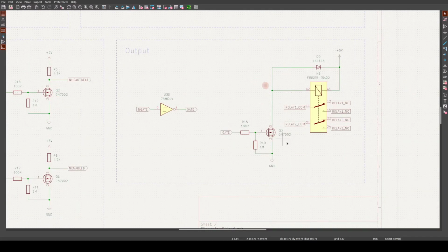This section handles the gate output. I decided to provide the output in the form of a double pole double throw relay. This is a really flexible form of output. I can use it to switch 2 circuits at different voltages or different ground potentials if necessary.